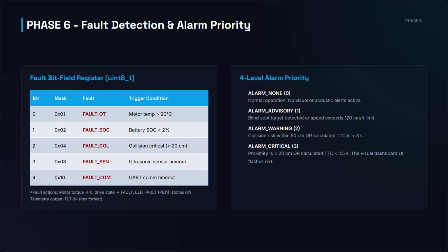Then we have the faults themselves; we have 5 faults in total. That is, motor temperature greater than 90 degrees Celsius, SOC less than 2%, the collision faults that we saw earlier, and UART timeout, where the ultrasonic sensor values are not getting updated properly. We'll have all these faults.